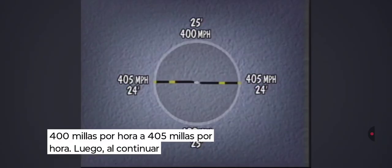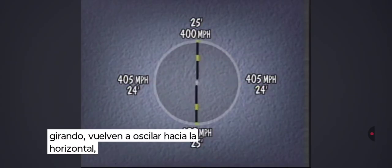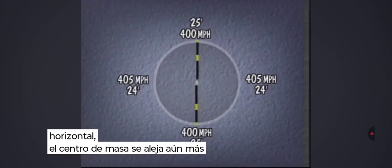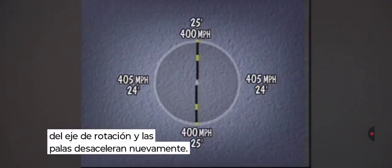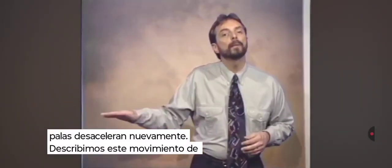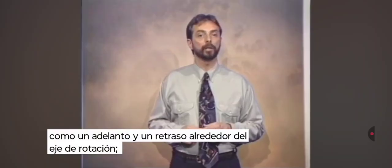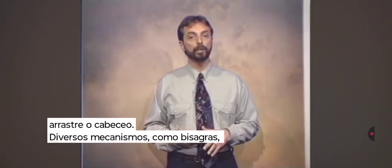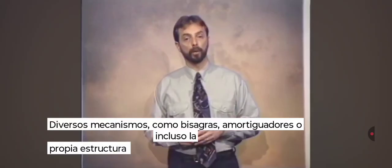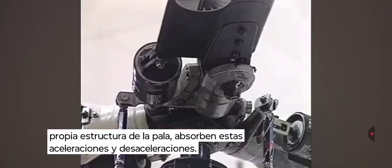Then as the blades continue rotating, they again flap towards true horizontal. The center of mass moves further away from the axis of rotation, and again the blades decelerate. We describe this back and forth blade motion as leading and lagging around the axis of rotation. It's also called dragging or hunting. A variety of hinges, dampers, or even the blade structure itself absorbs these acceleration-deceleration actions.